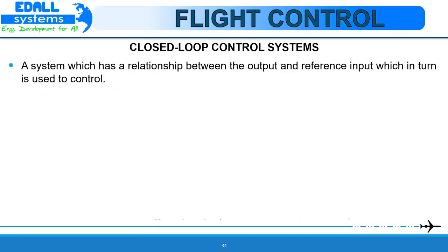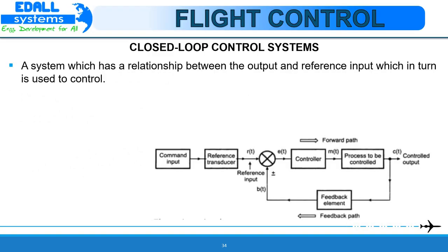Now to closed loop control system. It is a system in which the controlling action or input is somehow dependent on the output or change in the output. To have dependency of input on the output, such a system uses a feedback property. Feedback is a property of a system by which it permits the output to be compared with the reference input to generate the error signal, based on which the appropriate controlling action can be decided. In such a system, the output or part of the output is fed back to the input for comparison with the reference input applied to it.